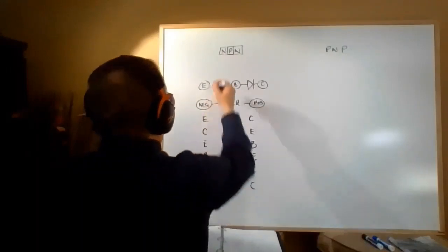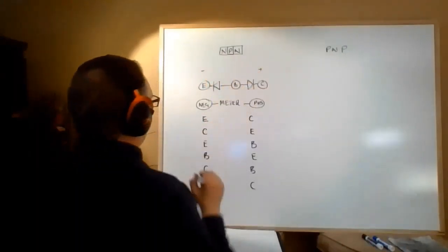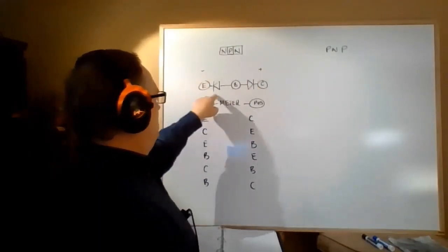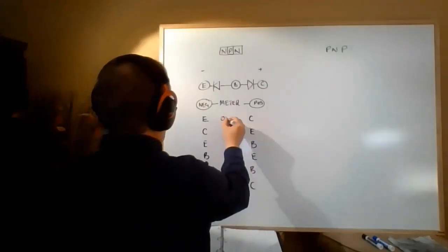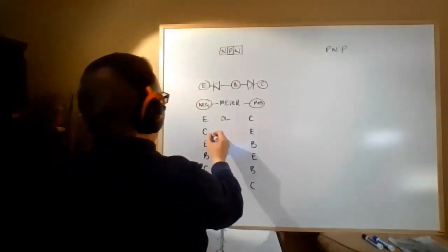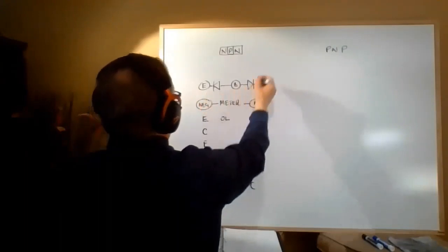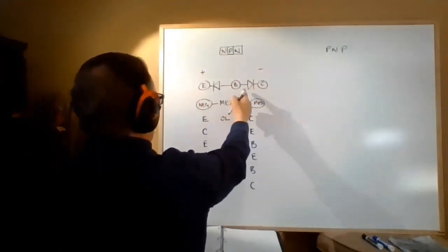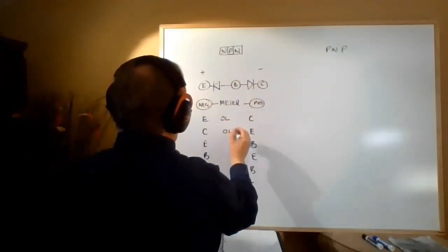So let's double check our points, okay? So negative, positive. If we put negative here and positive here, what's going to get through this arrangement of two diodes back to back? Absolutely nothing. And so this is going to be OL, okay? What about if we go from C to E? Well, guess what? Because either way, so here we put negative and positive, either way you look at this, one of them is going to block. And so that is also OL.